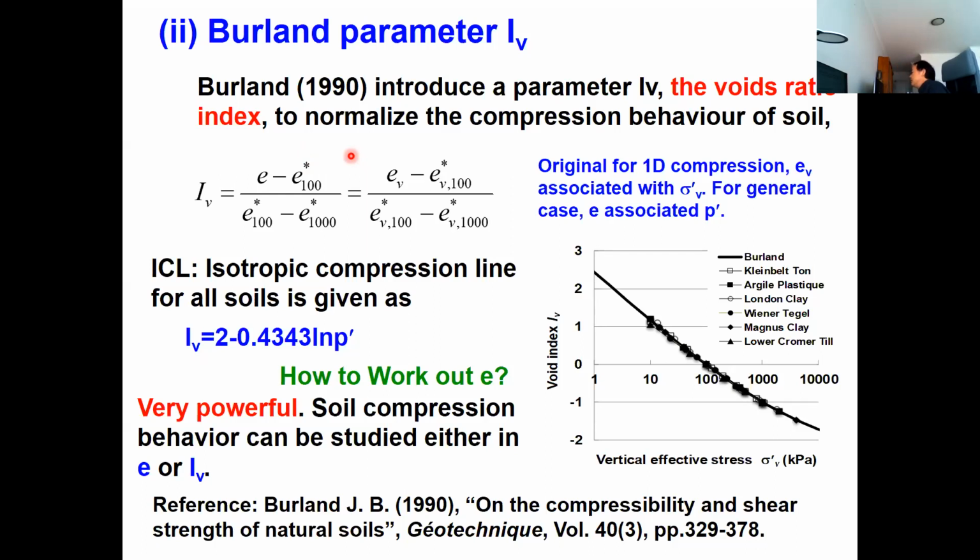Your boat is only good for water travel. It's the same way: the Cam clay model is only good for reconstituted soil. So you need to know what reconstituted soil is. If you find that the data is not reconstituted soil, don't use the Cam clay model, just like you don't drive your car into water.